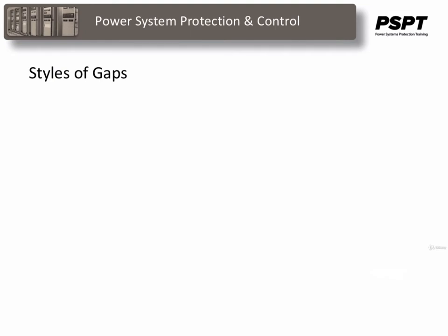One of the simplest forms of surge protection is the spark gap. It will break down at a predetermined voltage, but will not usually extinguish itself. So the interruption of power current flow depends upon some current limiting device, either a fuse or regular station protective relaying or switching. Spark gaps are usually used to ensure that the voltage level at a station is below that of the apparatus with the lowest impulse voltage level. These are frequently used on a system because they usually are more economical than expensive arresters.